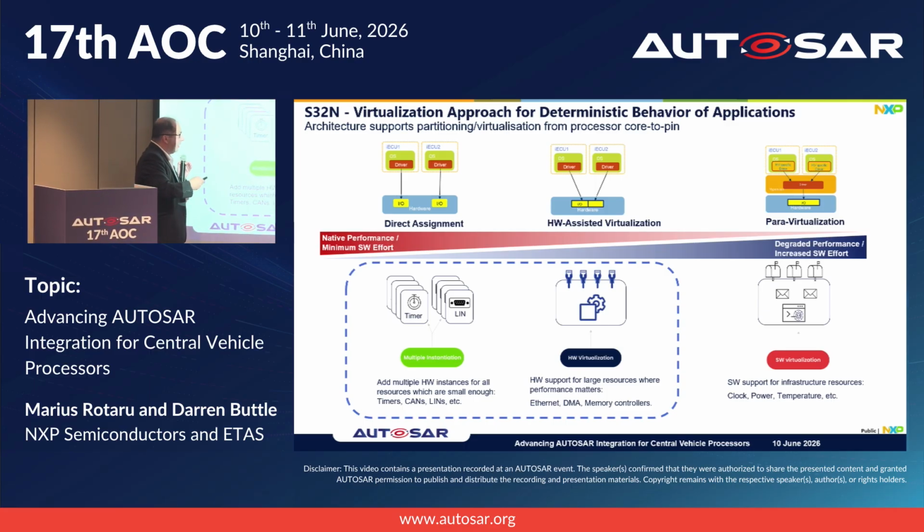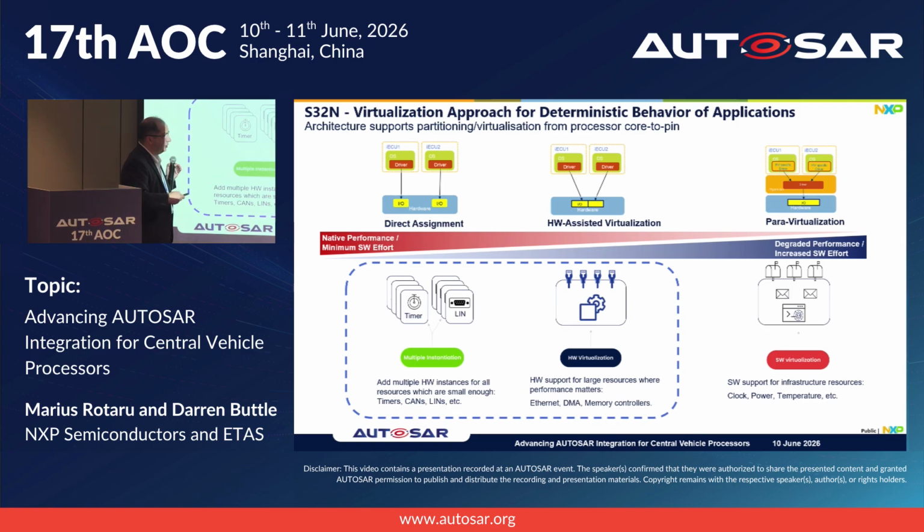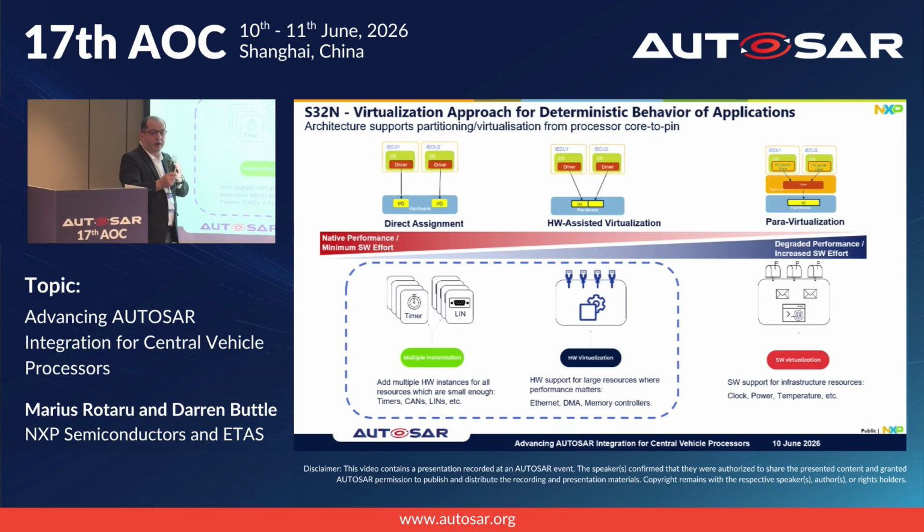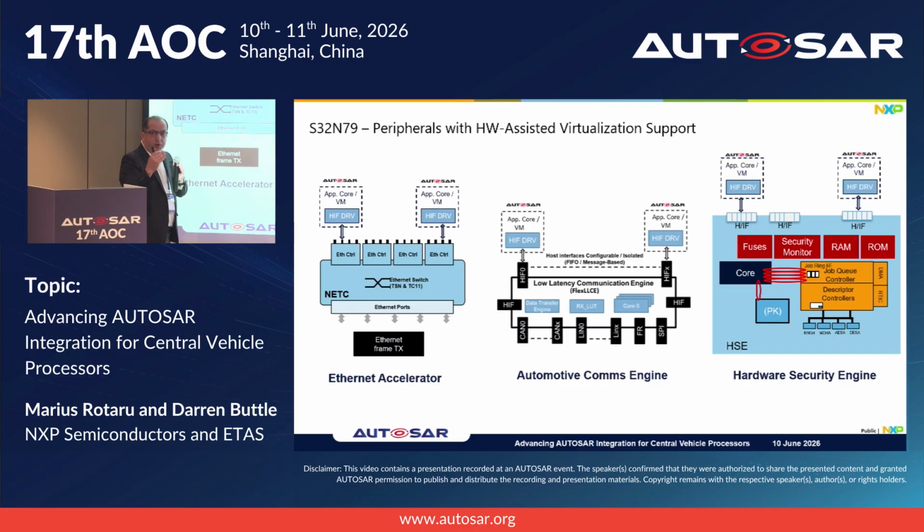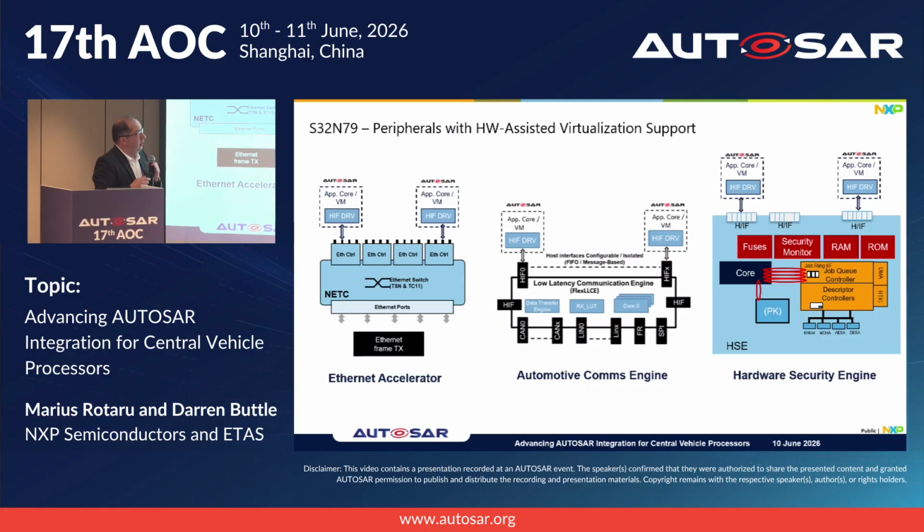Our device S32N has been designed to provide partitioning and virtualization from processor core to pin, meaning that we designed it to have multiple instances of the same peripherals, or we designed it mainly to address hardware virtualization using the hardware-assisted virtualization. So in other words, instead of doing virtualization in software, we did virtualization in hardware, and we do the isolation between these multiple interfaces. These are examples of peripherals which provide hardware-assisted virtualization support.